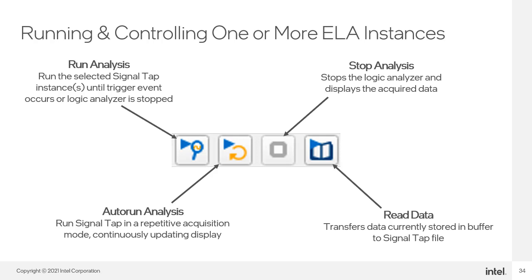It stops the logic analyzer from continuing to look for the trigger conditions. You may want to use this if the trigger conditions are not occurring. The data samples currently in the buffer will be displayed when you stop the analysis.